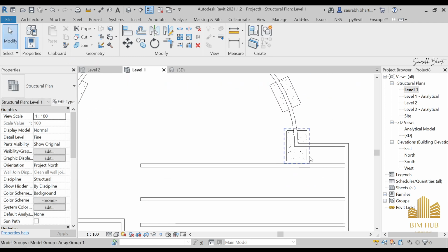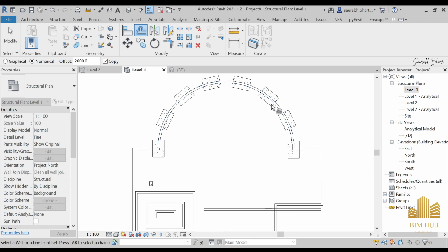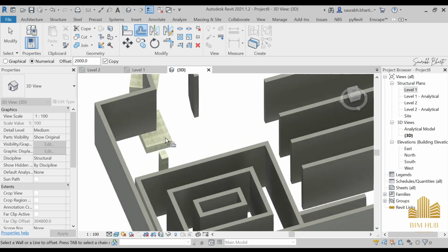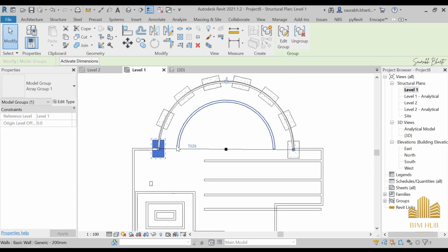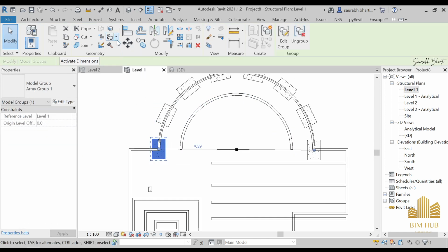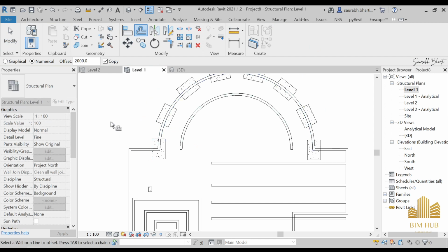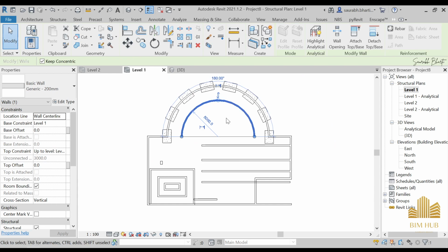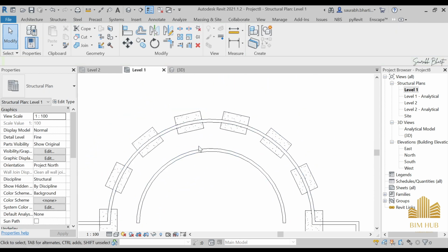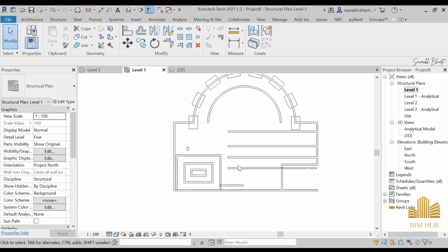Then you will see that the same thing has been made over here. If I do the same offset with, okay, I cannot actually select it. As you can see, I'm just selecting this wall. You will see that this has been made as an offset. And what if I try to select this one? No, I cannot make it offset in 3D view, but from here I maybe can. Okay, let's just leave that. So this is the offset option. You can draw anything at a distance that you want, and it will draw the exact same thing from that place.